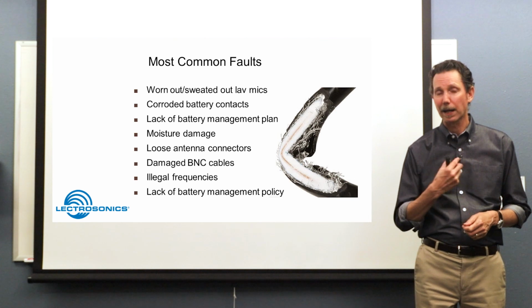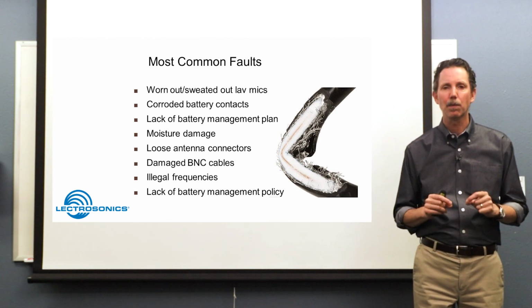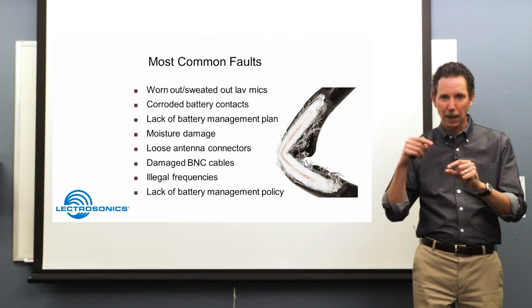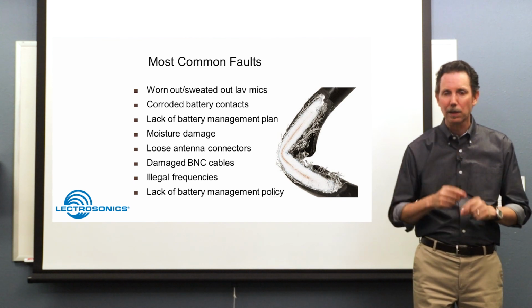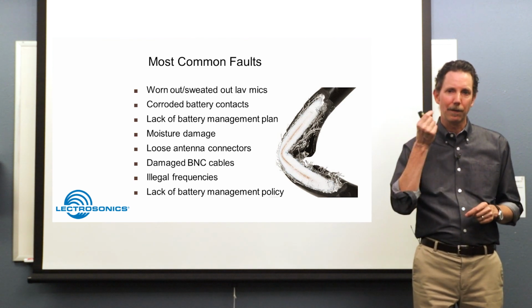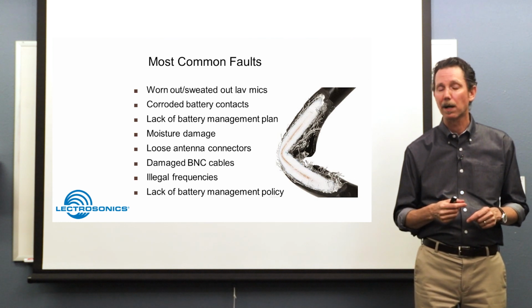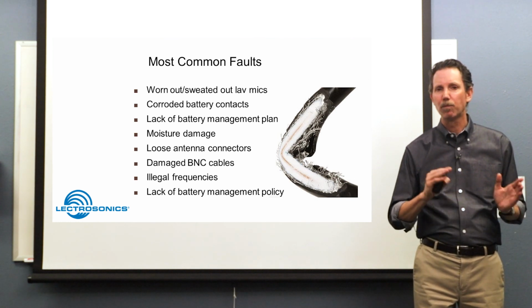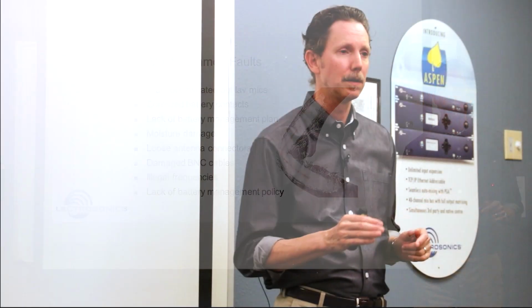As I said, lav mics, in some ways, and head-worn mics, they have that very thin cable. The connectors and the cable where the cable goes in can be damaged. Those sometimes need to be cut off and re-soldered, re-terminated. But if it breaks on the element side, that's something that's very difficult, if not impossible, to repair. So it's a good idea to have enough budget in your annual budget for equipment to have a little extra to make sure that you have good, relatively new and clean and operational lav mics and head-worn mics.